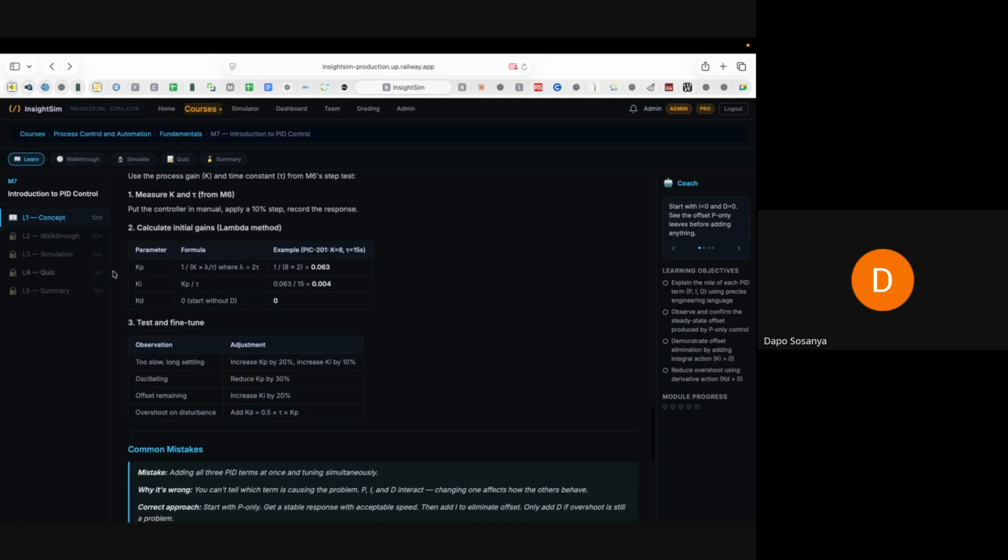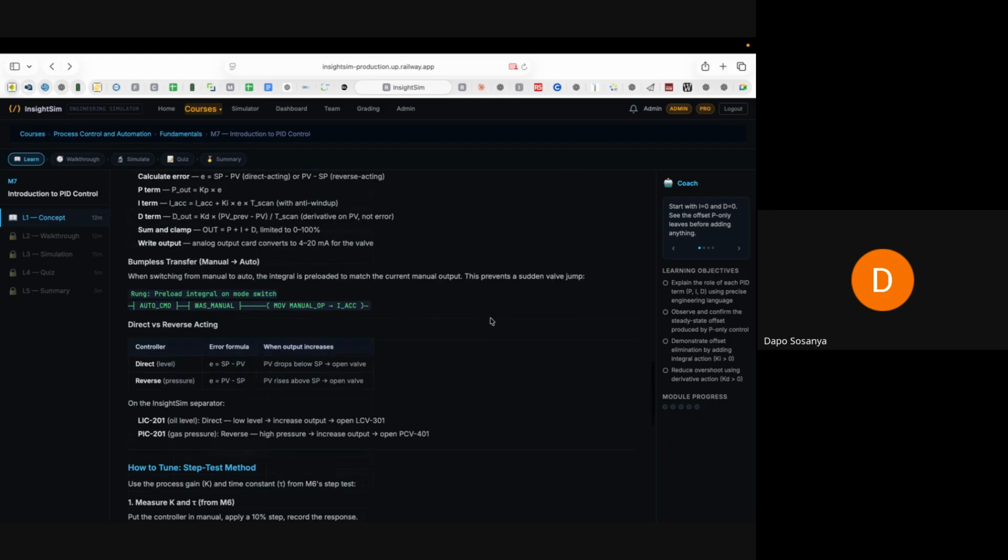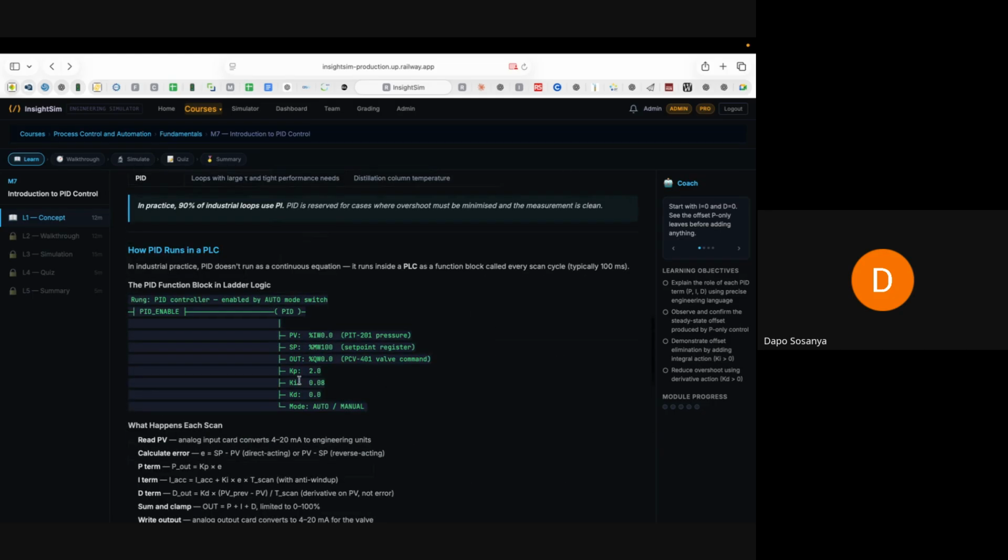And then you have your KP using this equation, and then for PIDs now, right? This example is taken from the separator process, right? And then you have this value. So this value for KP, this value for KI, right? And then that is what you will now put inside your program. So your KP will now be that value, your KI will now be that value.